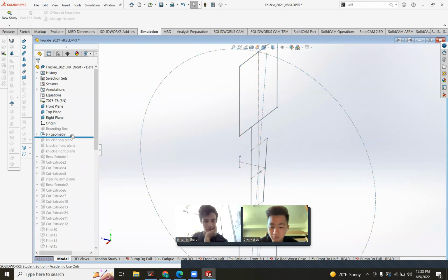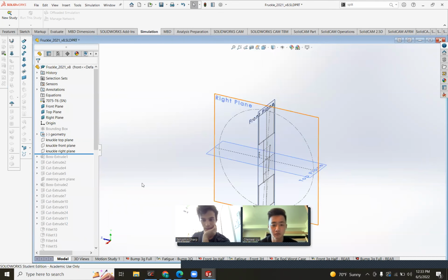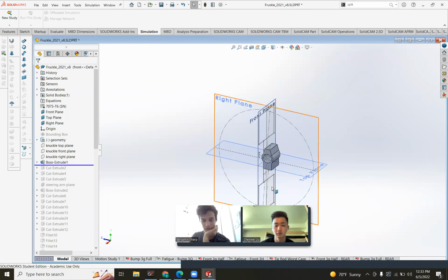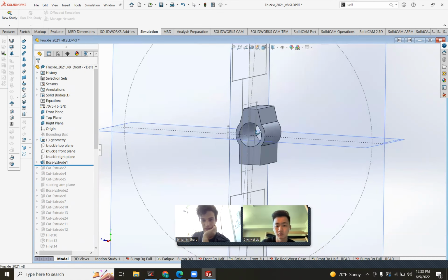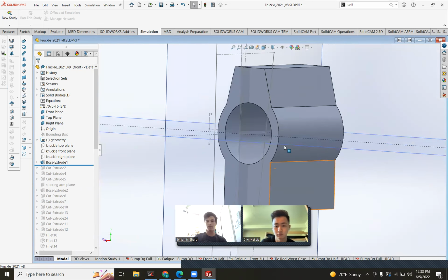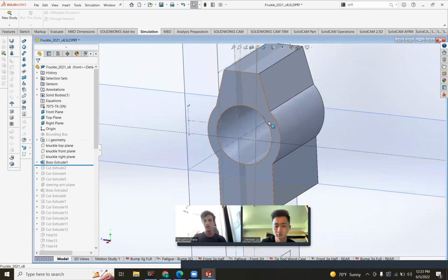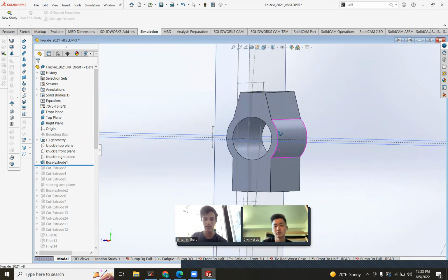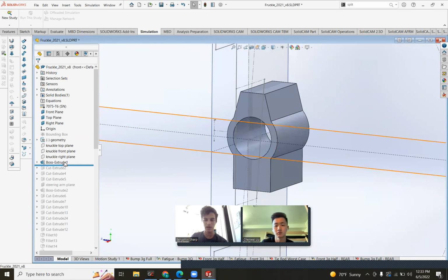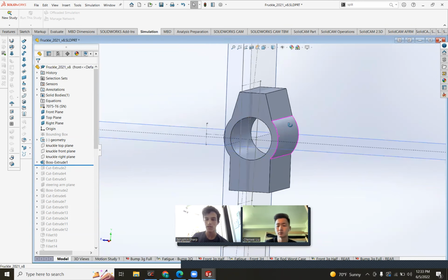Okay, so you start with geometry. I went ahead and defined some planes first thing based on the geometry. And then your first extrude should be the general outline of the bearing cup and the shape you want the knuckle to take from a front profile. So you're kind of thinking in terms of a CNC. If you are cutting this out of a piece of stock, this is the first profile, basically, plus the steering line. So start here.